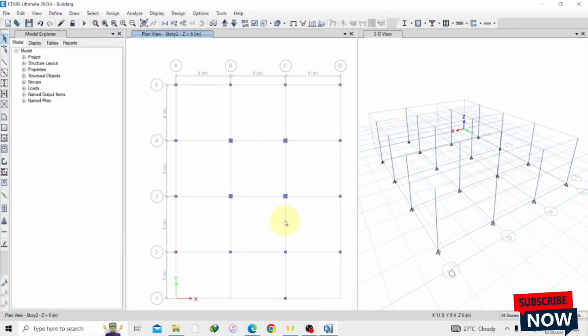So I'm going to teach you something very simple we are using to create that staircase area. This is 6,000, but we only need 3,000. That's like 3 meters for the staircase. So we are just going to offset this point 3 meters in this direction to get that point where we can also place our columns at that area.